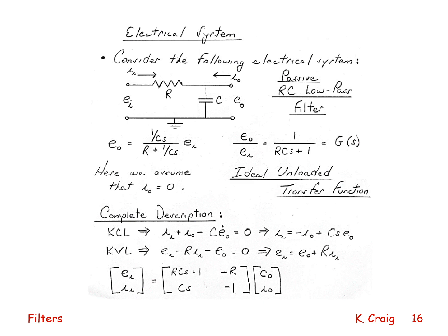Let's look at this a little more closely. Here is our RC low-pass filter. It's passive, right? There's no op amps in our filter. It's a resistor, a capacitor, and we have 2 ports, an input port, voltage and current, product is power. An out port, voltage and current, product is power. In order to completely describe this behavior, we must relate the input variables, voltage and current, to the output variables, voltage and current.